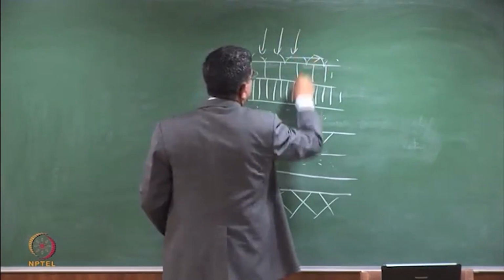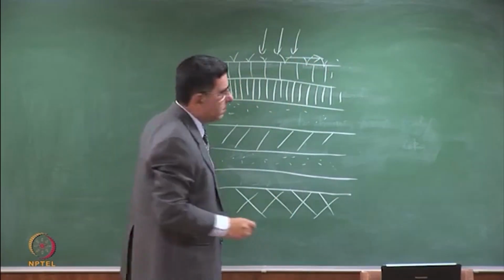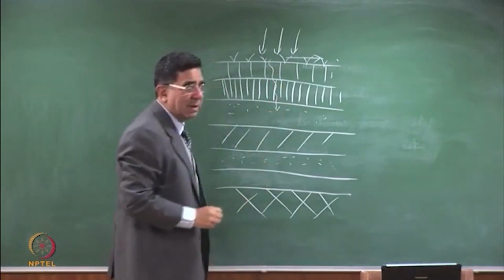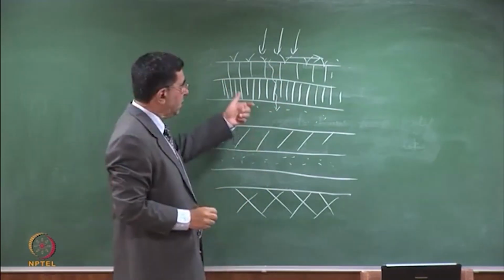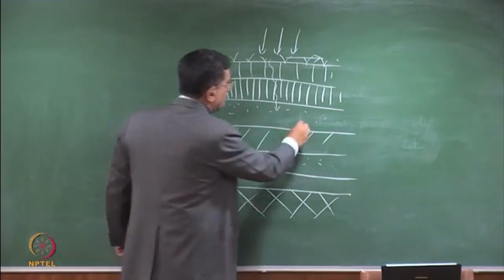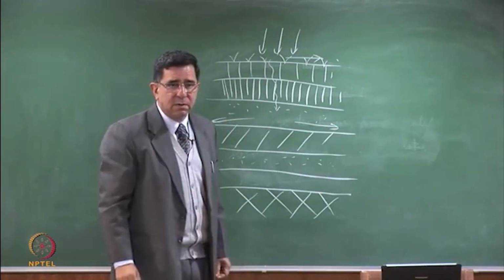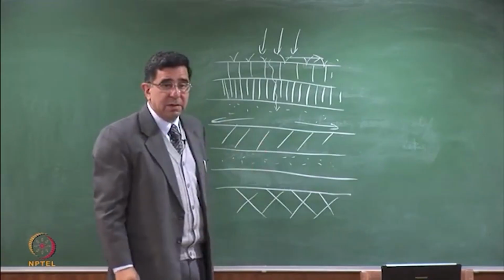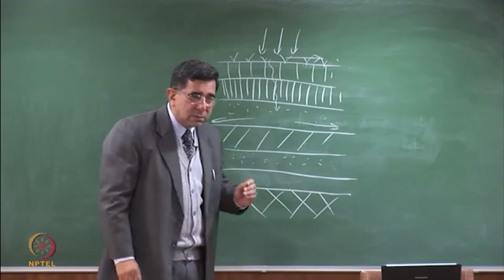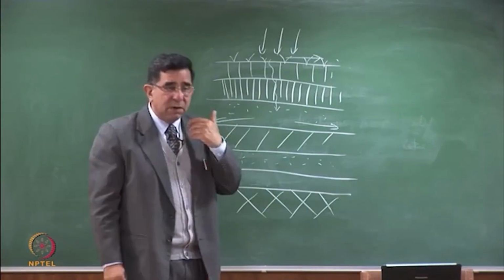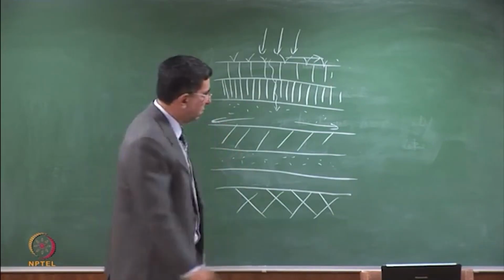If this is sloping, rain will run off. Some of it will come in. What will happen here at the barrier? We have put a drainage layer with a very specific purpose that this will also run off. We have a clay barrier. Something may go through, what we may call leakage, or we are designing it so that something should go through.